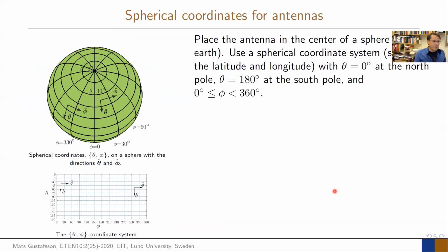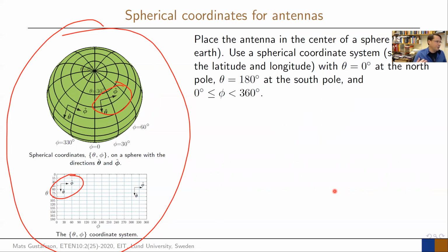And if I now put in my directions, it means that I sit on the sphere, and we know that now our antenna is perpendicular to the radial direction. So it will be in two coordinates. One, I point now theta angle, increase theta, it goes down, increase phi, it goes around. So these are my theta and phi directions. If I draw it on the wall here, it points like this. One points straight down because theta is increasing when I go down. Phi is increasing to the right, so phi points to the right. That is my coordinate system when I draw this. And we can draw antennas in either of these two. That is just two different ways of plotting the radiated field.